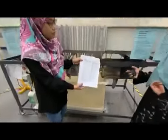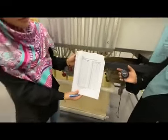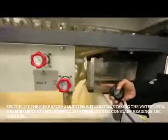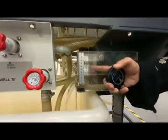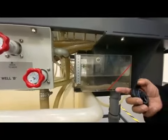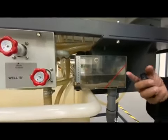Okay, once we reach the 120 seconds, we need to stop the pump. But the flow will still continue. So when we stop the valve, you will see the reduction of the water level. You need to calculate the reduction of the water level based on the 10 seconds, similarly like what we have done previously, until the last 3 readings are constant. Then you can stop the experiment.